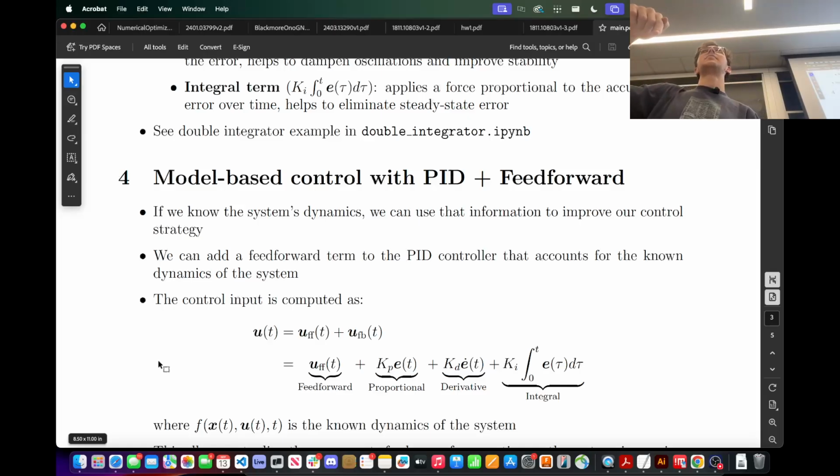So might as well apply an upward force, and I'll show you mathematically why this works, but intuitively we can say we want to apply gravity, the mg upwards, and then anything that's remaining, that's an error, we will apply feedback on.